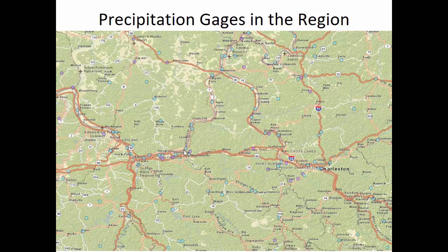So depending on the site, some sites may go back only 10 or 15 years, and in some cases we can find locations where there was maybe 20 or 30 years worth of precipitation data when they had a volunteer at a site, but now they're not gathering the precipitation data at that site anymore. And so sometimes we have to use precipitation data at locations that surround an area of interest and then make interpolations or estimate how much rain there would have been in this spot in between based on triangulating how much rain we saw in Barboursville, West Hamlin, and Hurricane, and then kind of just interpolate in between.